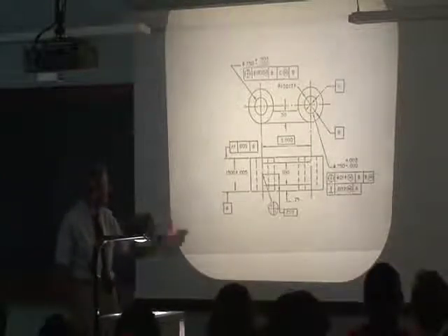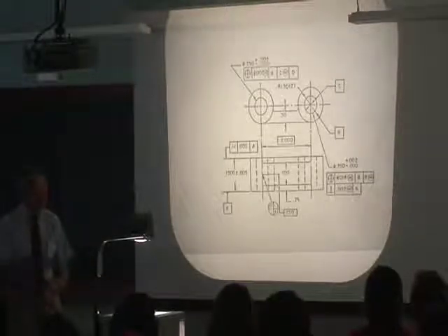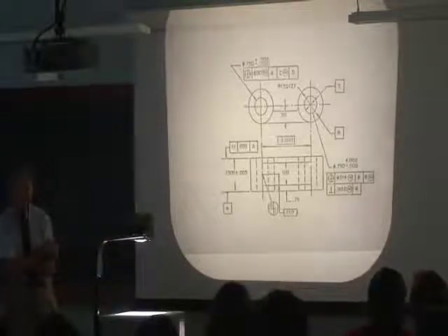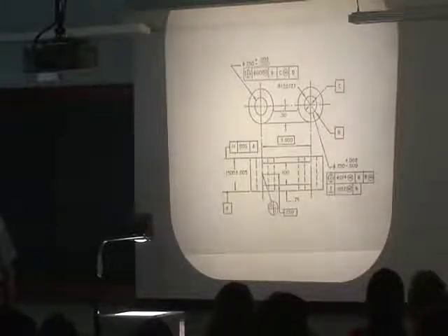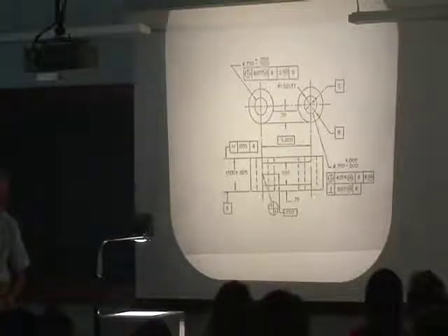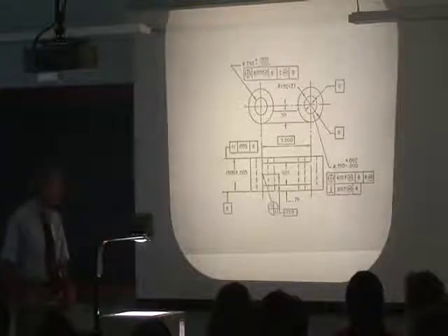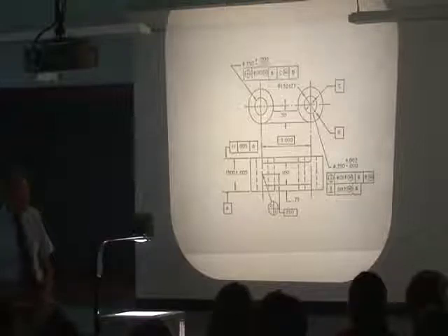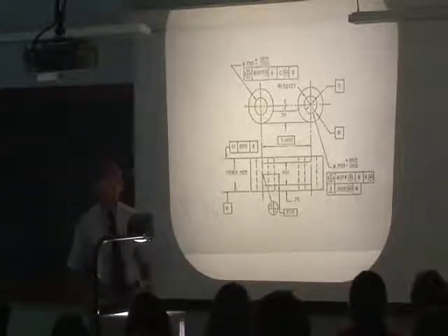It's tough to teach this in industry. It's difficult to teach it to university students. And the old system of these plus and minus tolerances on dimensions is still used in low precision industries. For example, in building construction, they're okay. You will probably be able to get by on those in most, perhaps all, of your sophomore projects. When you get into senior projects and start building race cars and things like that, you're going to be driven to this. And this is happening now in the Sibley School.